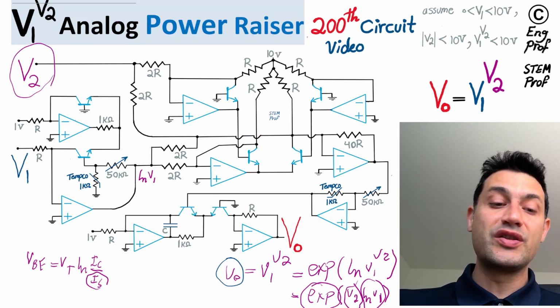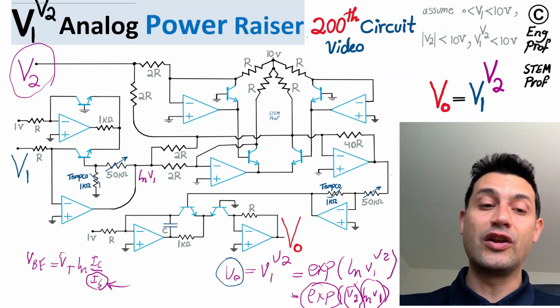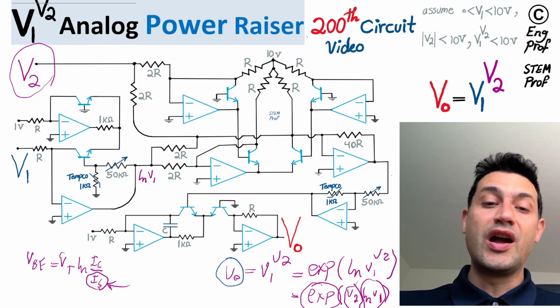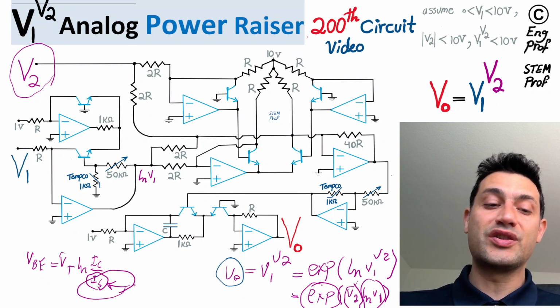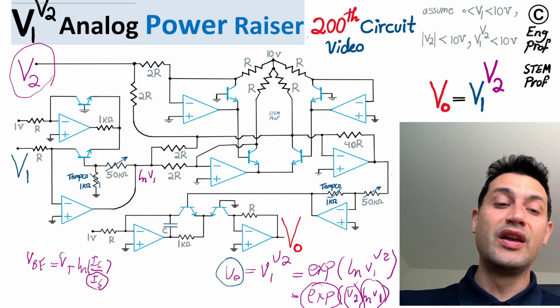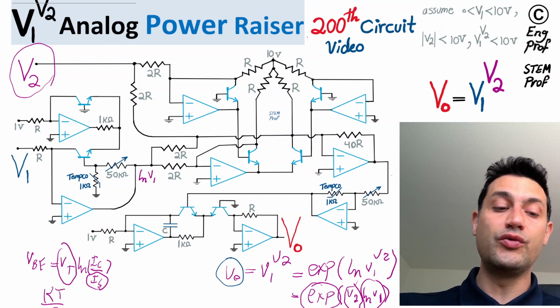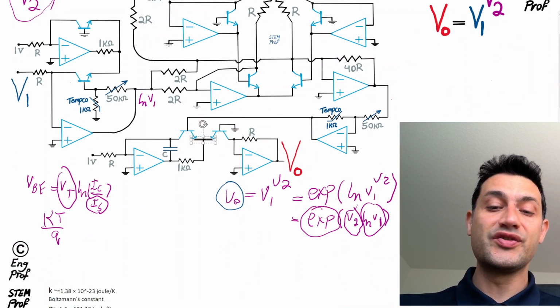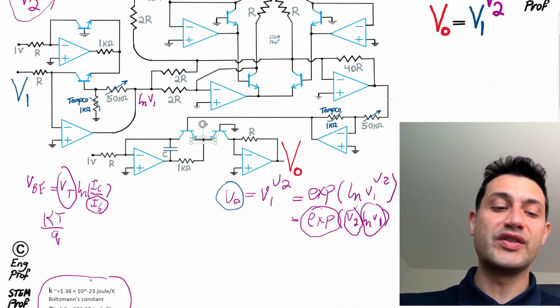The saturation current depends heavily on temperature, varying a lot with temperature and process. So the circuit is designed in each subcircuit so that we get rid of this saturation current as soon as possible. That's one important step. The other one is the thermal voltage, or VT, which is just kT over q, in which k and q are the Boltzmann constant and the electron charge. So these are well-known constants, of course.